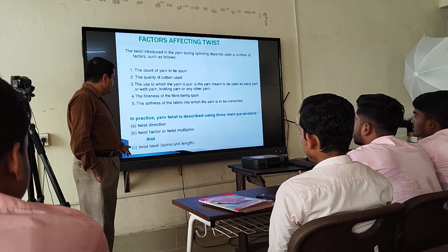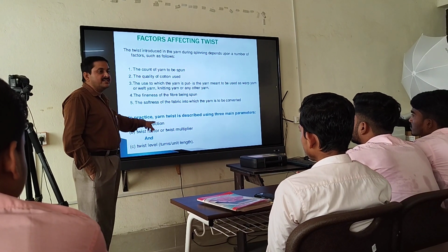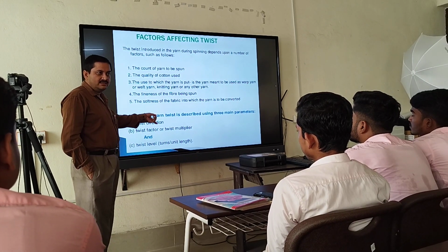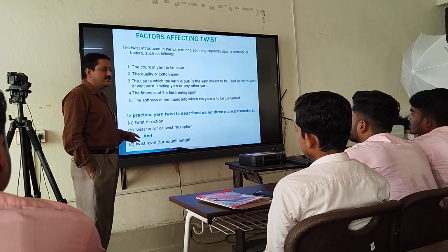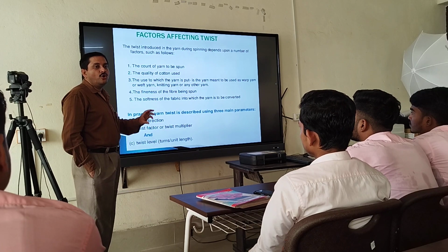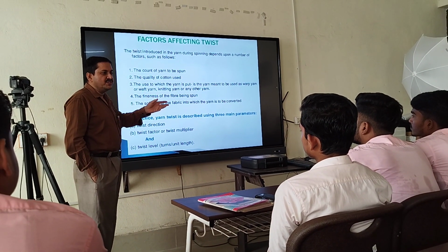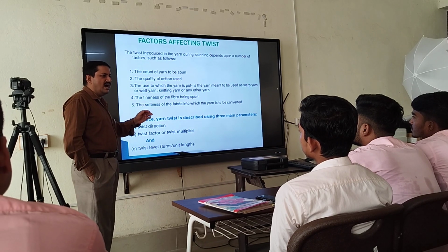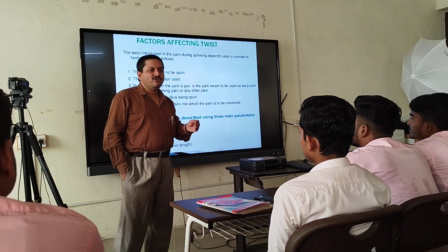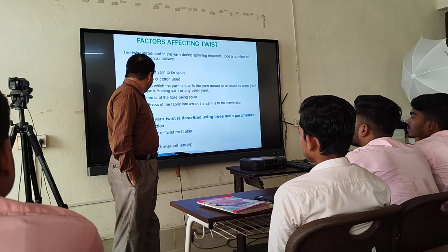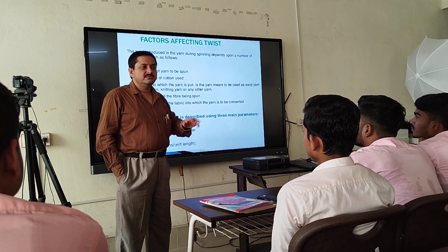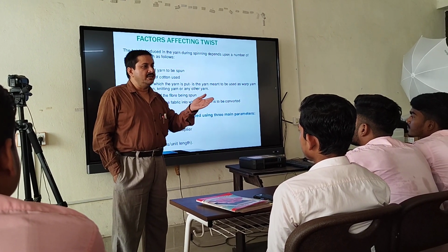So three important things, please listen. Twist direction, whether it is S twist or Z twist. Another is your twist factor or twist multiplier. Different schools of thought express this terminology differently. Some people call it twist factor, some people address it as twist multiplier.